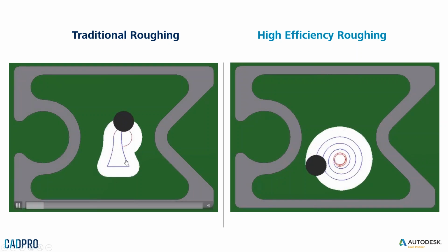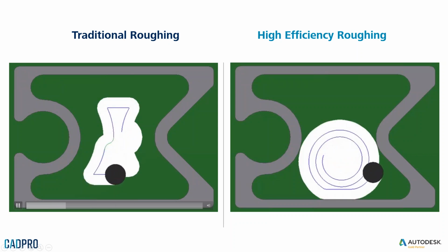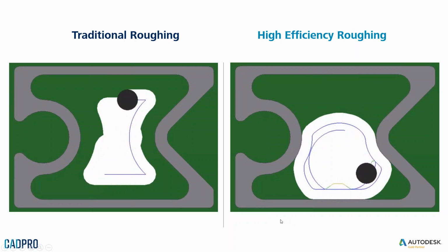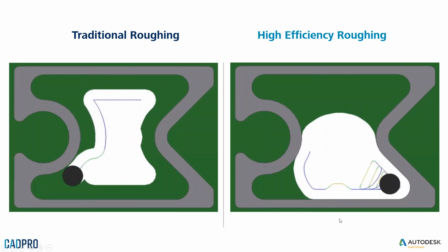In plastics and even in aluminium in some cases, this toolpath on the left is still quicker. And then on the right here, in harder materials, you're going to get much better run times.